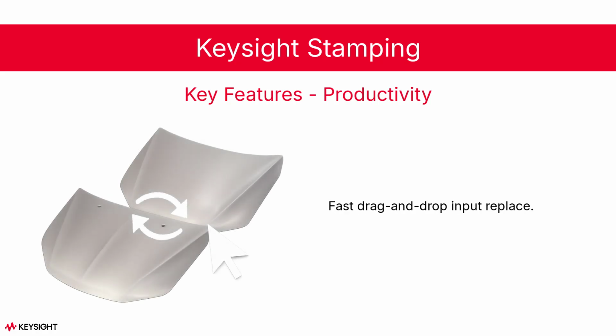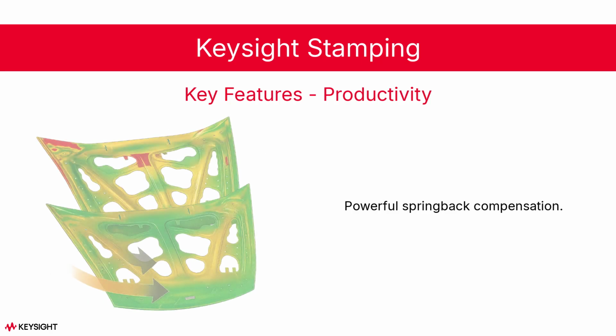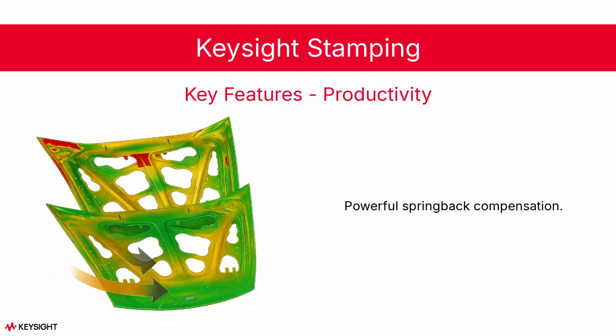To efficiently handle model iterations, a dedicated drag-and-drop interface is provided, preserving each object's original CAD naming to ensure fast and accurate identification during stamping simulation setup. PAM-STAMP also offers powerful automatic spring-back compensation, applicable to a single operation or multiple operations, enabling components to meet geometric tolerances and greatly reducing the number of physical iterations during tryout.